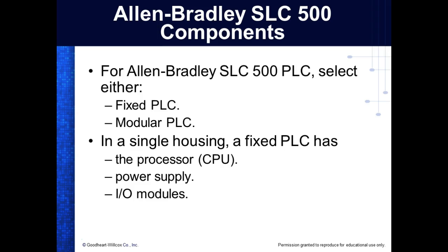And then this in the back, can y'all see this? This is called a backplane. And all it does is we take these modules and we plug them into that backplane. And then of course we have to tell our programming application what we have. Because RSLogix 500 is an application that Allen Bradley or Rockwell just changed over lately over to RSLogix 5000. So there's all types of PLCs out there that we program with that application.